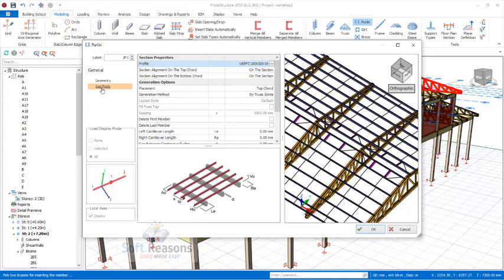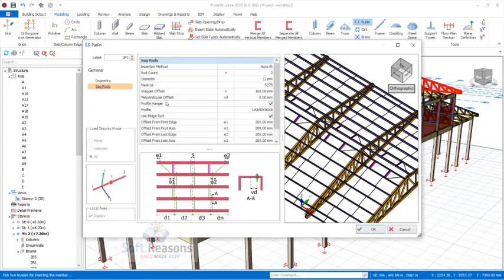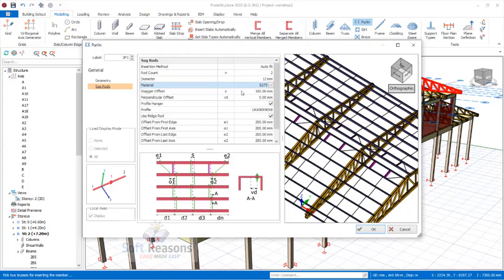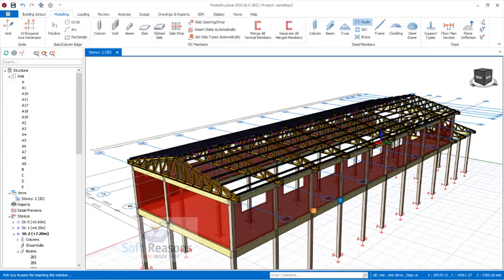For the sag rods, we have two kinds of sag rod, profile angle and the profile itself. Okay, so you can decide on which to use, and as well the diameter of the sag rod is 12 millimeters. The material of the steel we are using is 275 strength. So over in these provisions you can also change to any strength. Okay, but 275 is economical, and it is easily found in the market. Click on OK to place the purlins just like this.